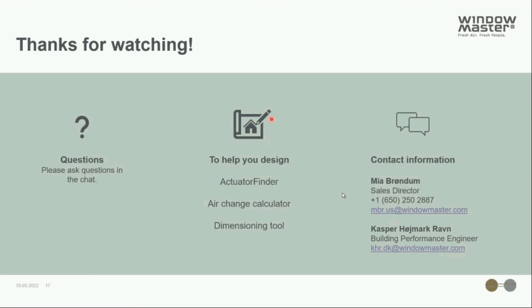Yes. I'm not an expert in the mechanical ventilation design, but in most mixed mode designs, the idea is that when we use natural ventilation, the mechanical ventilation will be deactivated completely. We see some scenarios, especially during colder times, where you are making a combined strategy, where, for example, if it's very cold outside, you're supplying the building with 2/3 mechanical ventilation, and then the last third with natural ventilation,